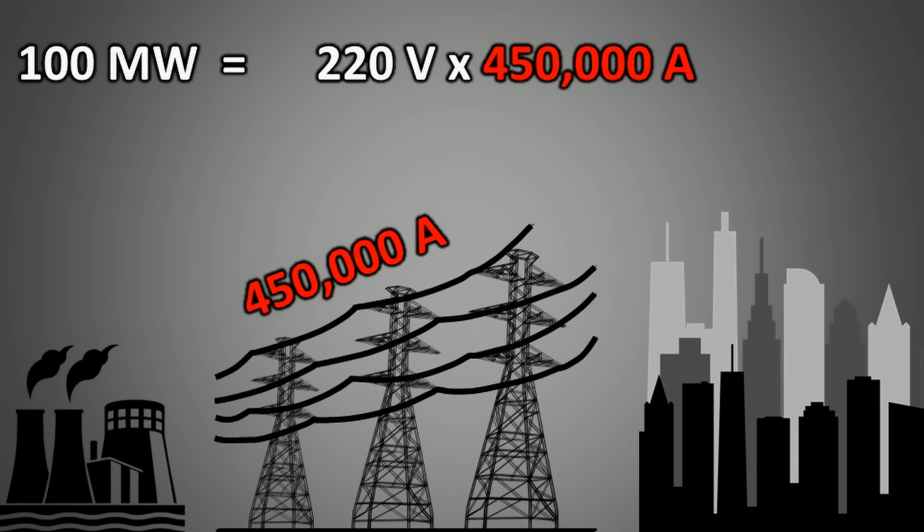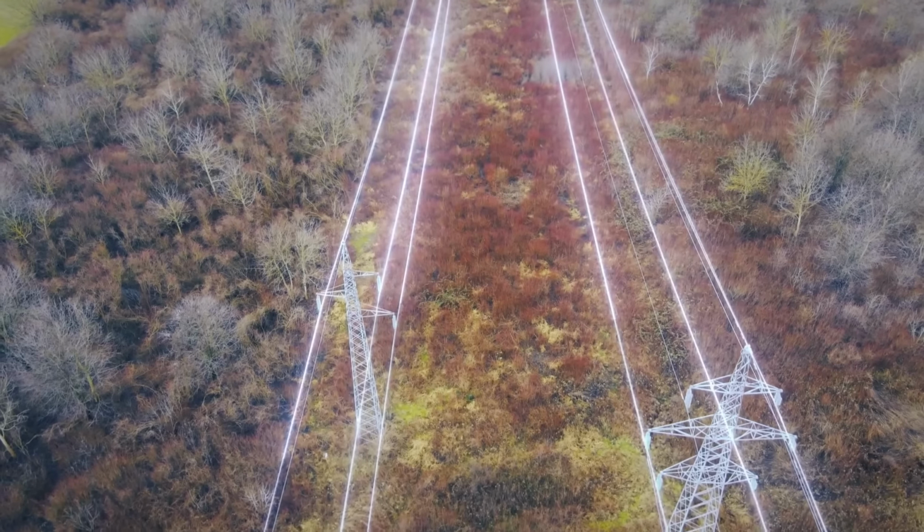To carry such a huge current, we would need extremely thick and heavy cables. This makes the erection of transmission lines extremely expensive. And not only that, when such a large current flows, Joule heating becomes very high. A lot of power will be wasted as heat.